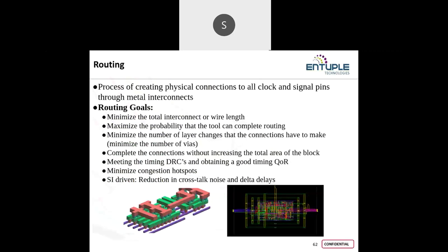One question is, what are the different techniques we can use to minimize the clock skew? See, the different techniques are nothing but what I am just telling: clock tree building and balancing. Additionally, we have the option to modify the predefined constraints that I set in the synthesis stage. Based on those constraints you can optimize skews.